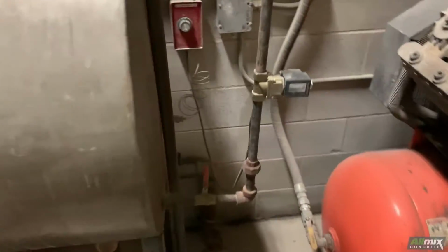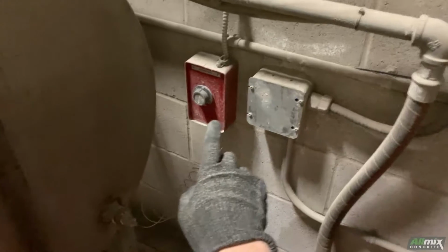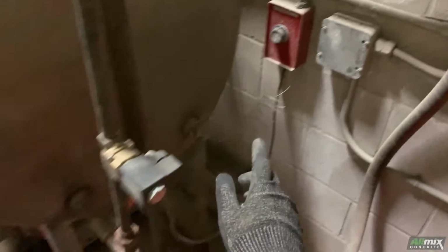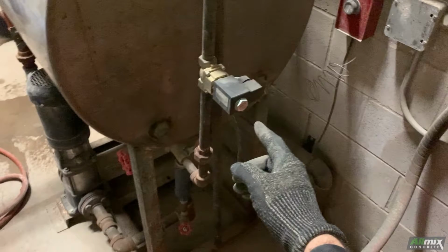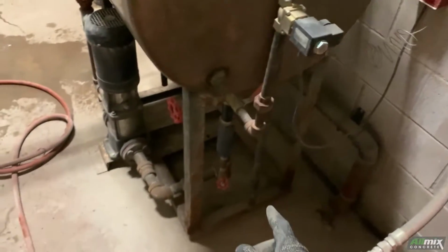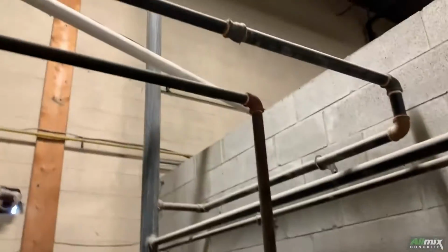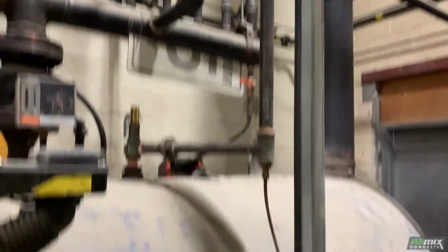The water enters the preheat tank or condensate tank, where it's mixed with steam from the boiler based on this calorimeter. The calorimeter measures the water temperature and activates a valve in the steam line to allow more steam into the tank. The boiler pump pumps the heated water into the boiler based on water level signals from the boiler control system.